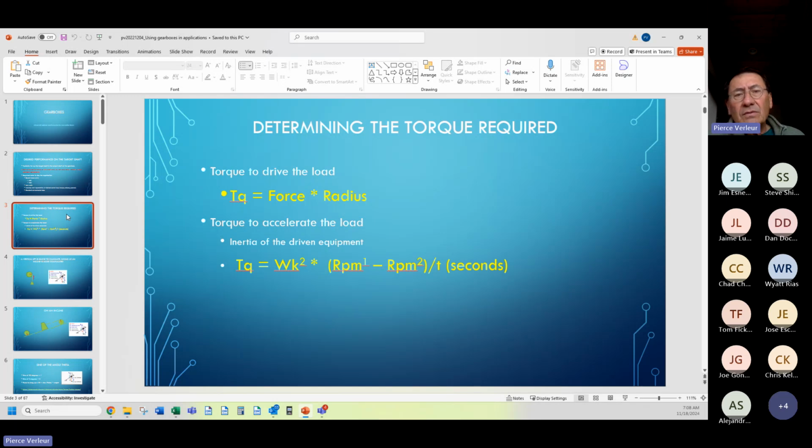An indexing move, going from point A to point B as fast as possible, is nothing but an accel and decel move. Because you're going from point A to point B as fast as possible, you're accelerating the entire time until you have to decelerate to stop on the designated point. There's no time to run at a constant speed. But there are a lot of applications like conveyors where you accel, you run at a continuous speed, and then you decel at the end of the cycle.